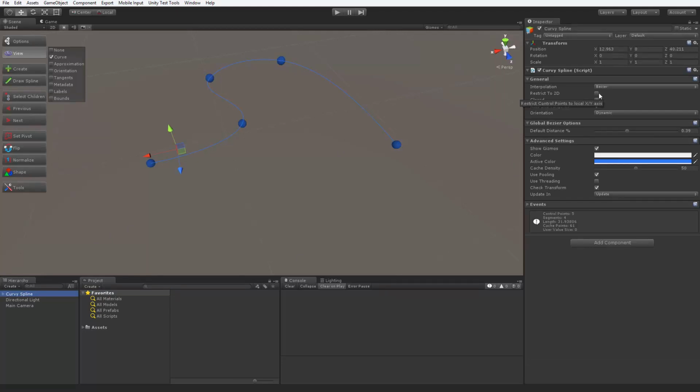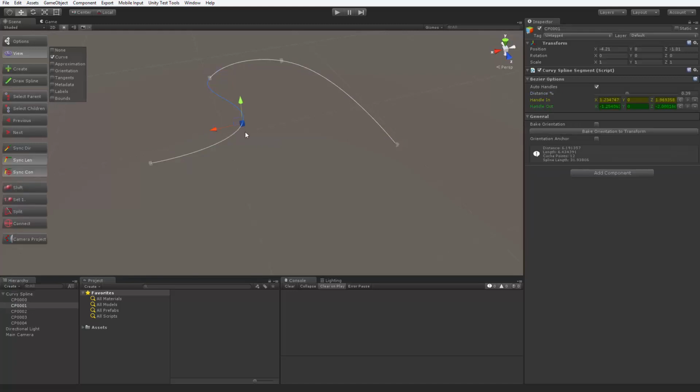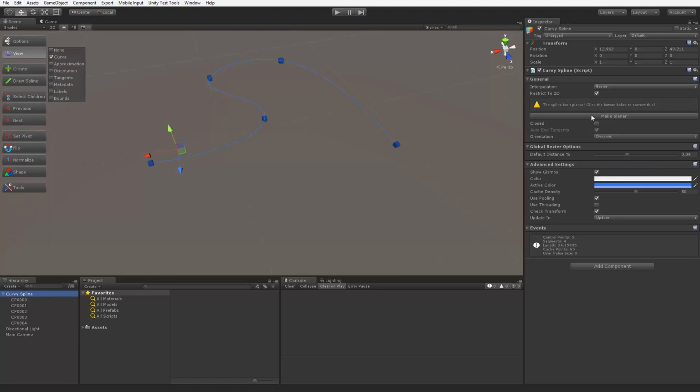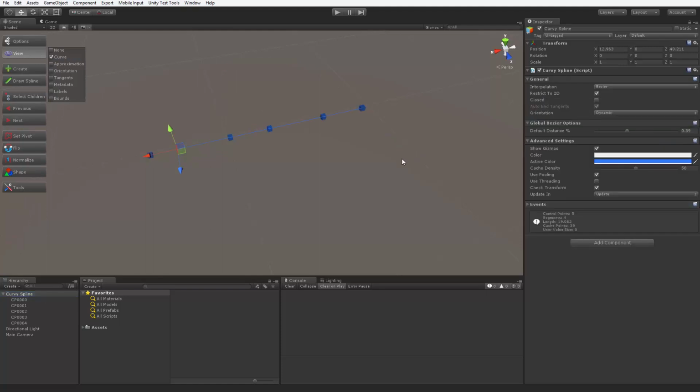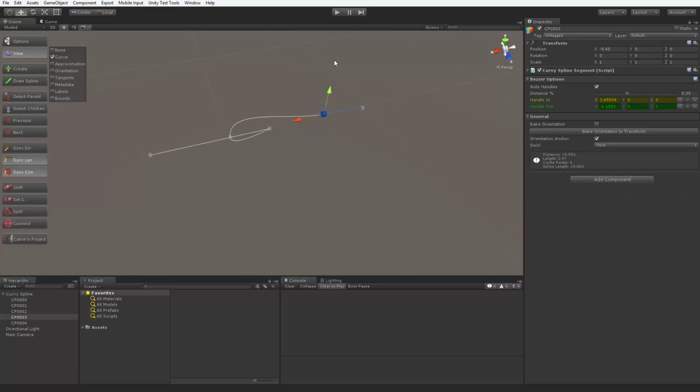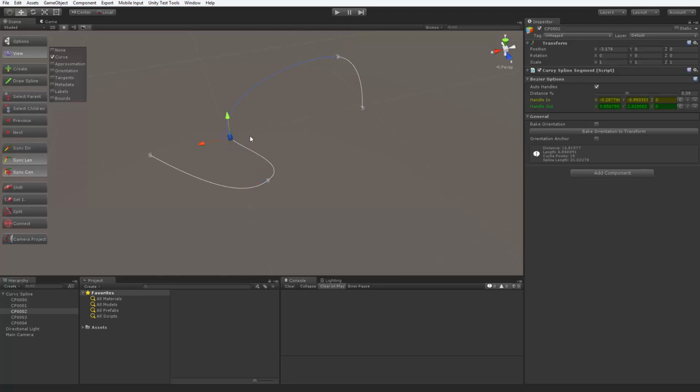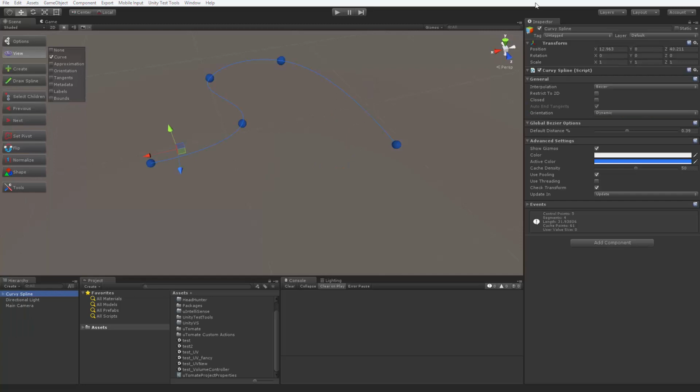It will switch the transform position gizmo in your scene view into 2D mode, prohibiting translation of control points on the Z-axis. This mode won't automatically set the coordinate of your points to 0, so that you won't lose any work when you accidentally click that toggle, but the inspector will warn you if your control points are not coplanar and will display a button allowing you to fix that. Splines restricted to 2D on the axis can be very useful for a number of objects, like UI elements and shape extrusion cross-sections. Next option is Closed.